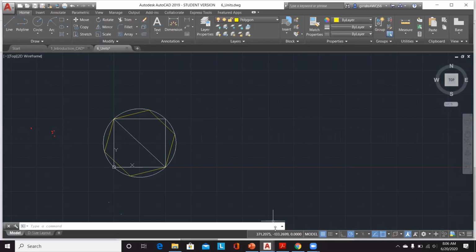If you search for the scale factor to convert 1 inch to 1 millimeter, the factor is 25.4. So if you want to model to scale in metric units, you need to scale the drawing by 25.4 and then add your dimensions to it.